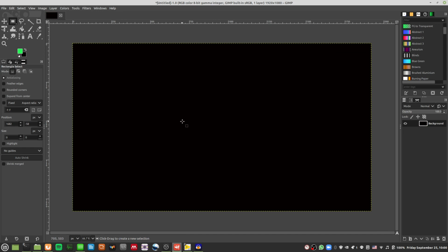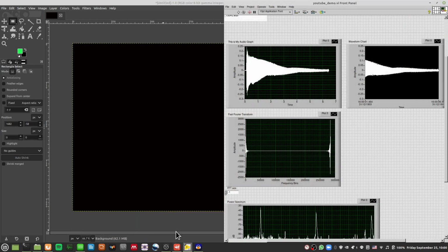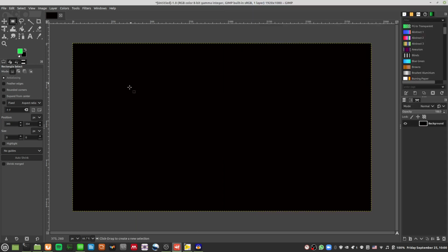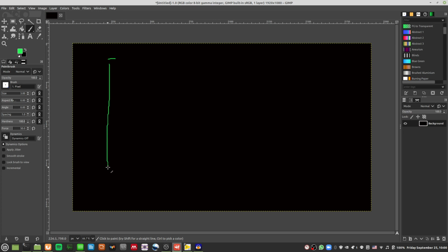But don't worry, even if you just left it as the default 0 or minus 1, such that LabVIEW will take the default matrix size n, or the default array size n, as your FFT size, that is still okay. As you saw, it was still able to produce a spectrum.